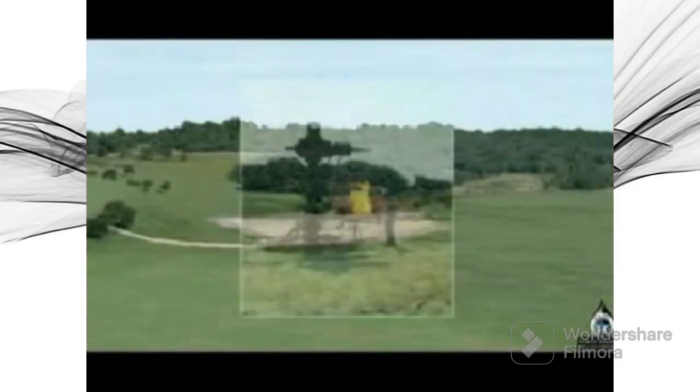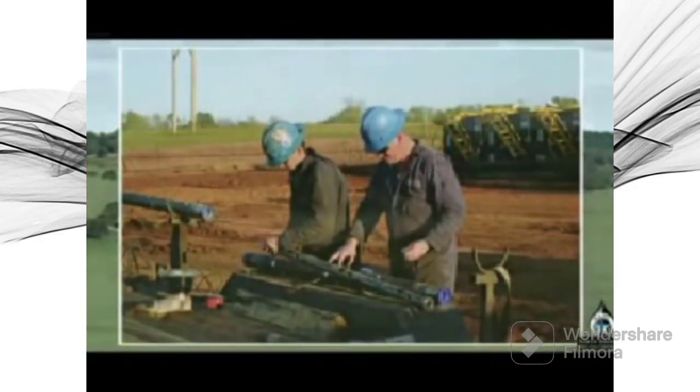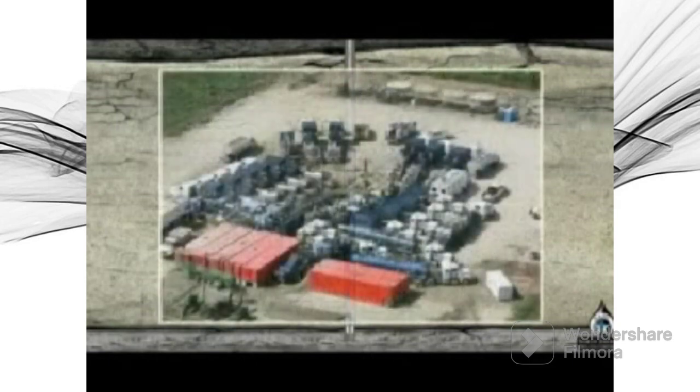Back on the surface, the drilling rig is no longer needed. A temporary wellhead is installed and the location is prepared for the service crews who are already there for a production job. The first step is to perforate the casing. A perforating gun is lowered by wire line to the lowest of three targeted zones. An electrical current is sent down the wire line into the perforating gun, setting off a charge which shoots holes through the steel casing, cement and out a short distance into the target formations. The perforating gun is then pulled out of the hole.